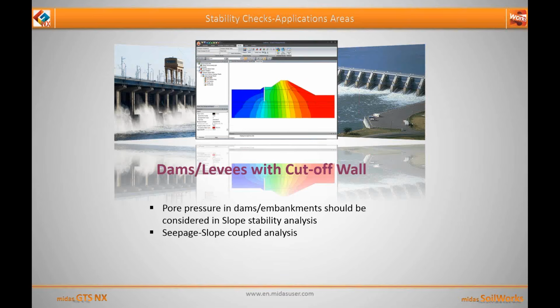Now, dams or levees with cutoff wall. Dams are basically a structure in which I think almost all the geotechnical analyses need to be performed, whether it is consolidation, seepage, or slope stability. But the important thing with slope stability analysis in dams is that you should be able to consider the pore pressure variation within the dam while performing the slope stability analysis.